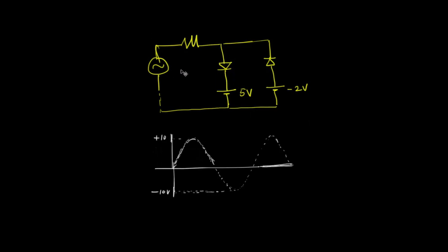of each other. So this has this part of a clipper. This is actually two clippers: this part of a clipper and this part of a clipper. The first part of the clipper says that all voltages below 5 volt will pass. You see, this diode is pointing downwards, so all voltages downwards of 5 volt will pass. So this is the 5 volt level, I suppose. I will just mark the 5 volt level. This is 5 volt.